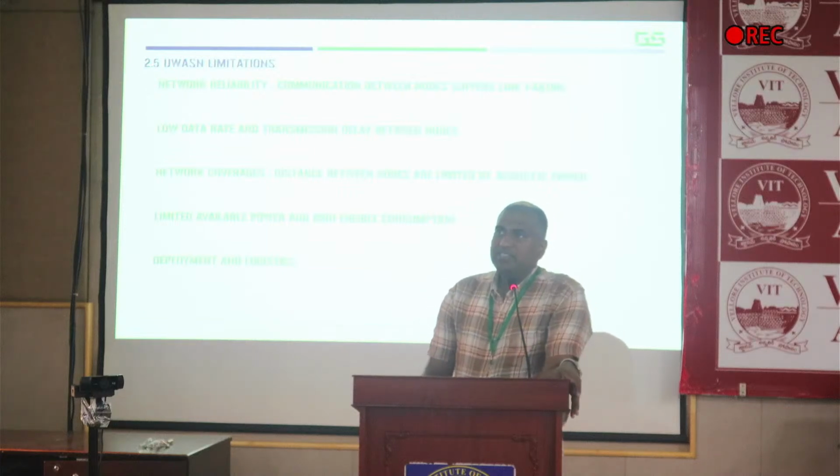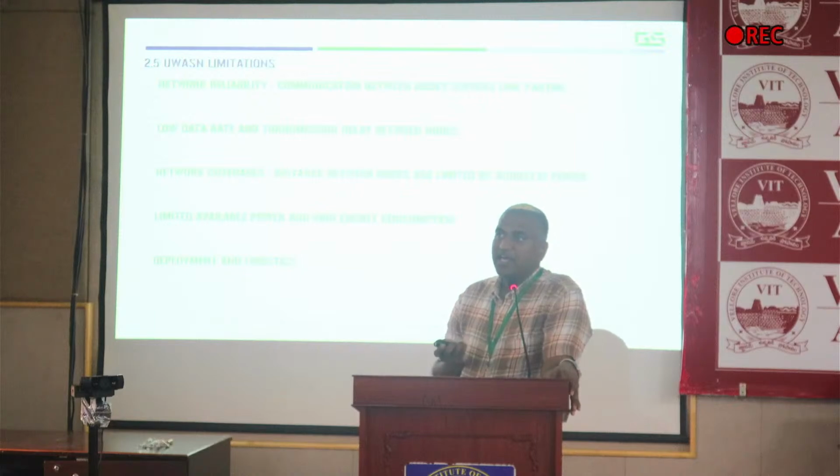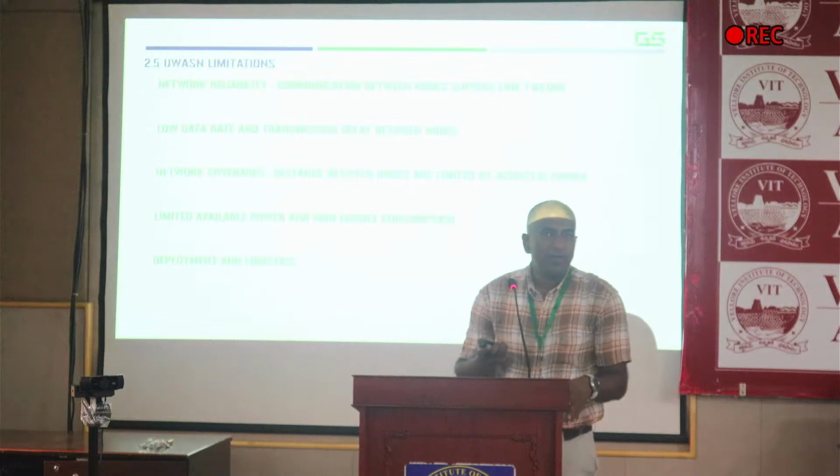So this UWSN has several limitations. Network reliability is one of the issues because links are not stable, and in underwater we cannot achieve higher data rates. If you want to achieve higher data rates, you should use powerful modems. When you use those modems, it is dangerous for the underwater mammals.